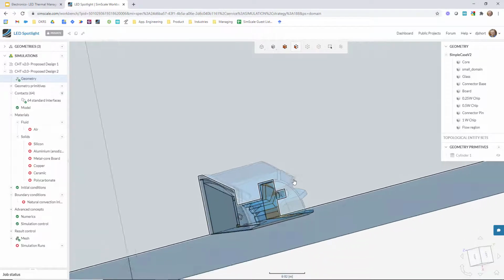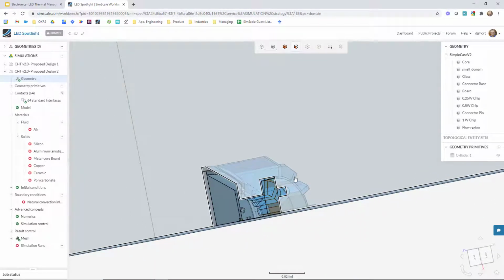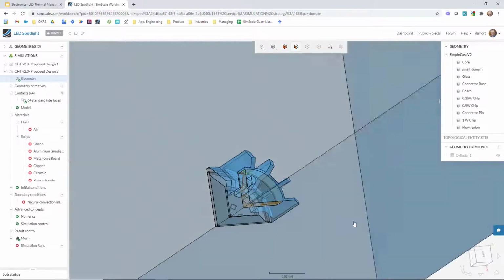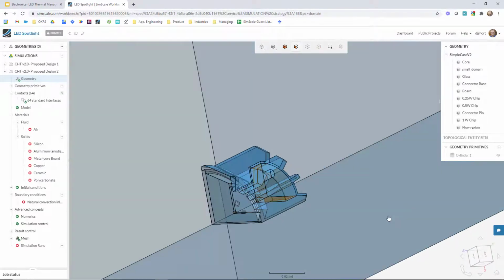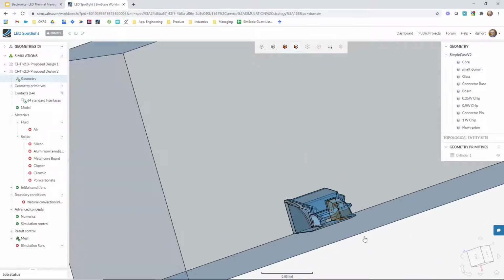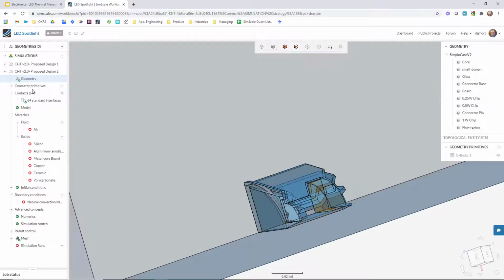And we can see that we've got some bulkier heatsink fins with a larger spacing as well. So when we assigned the new geometry, what it firstly did is automatically find the interfaces between both the solid parts and also between the solids and the fluid regions as well.